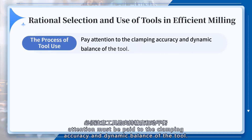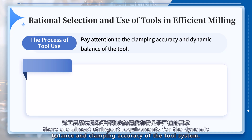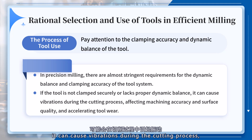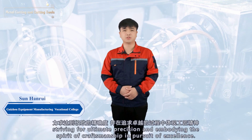During the use of tools, attention must be paid to the clamping accuracy and dynamic balance of the tool. In precision milling, there are stringent requirements for the dynamic balance and the clamping accuracy of the tool system. If the tool is not clamped securely or lacks proper dynamic balance, it can cause vibrations during the cutting process, affecting machining accuracy and surface quality and accelerating tool wear. This requires us to meticulously perform tool clamping and adjustment during the operation, striving for ultimate precision and embodying the spirit of craftsmanship in pursuit of excellence.